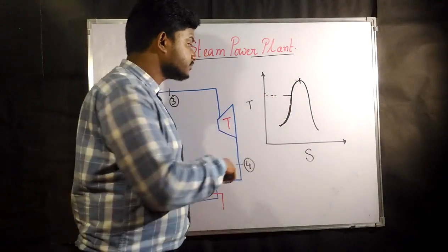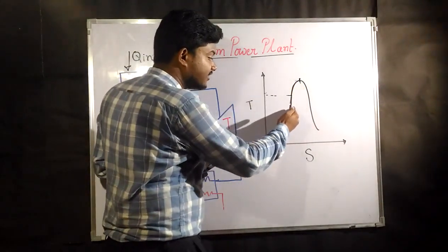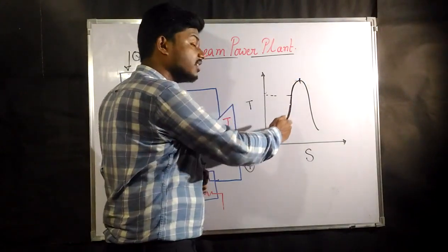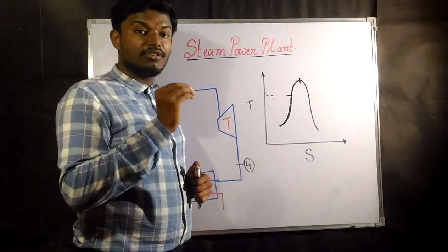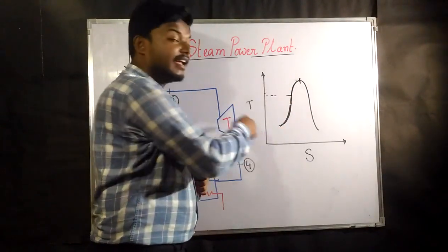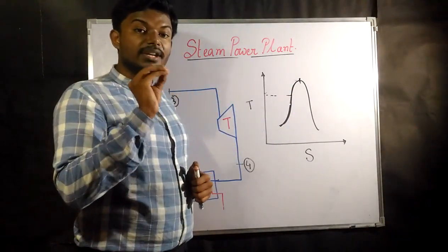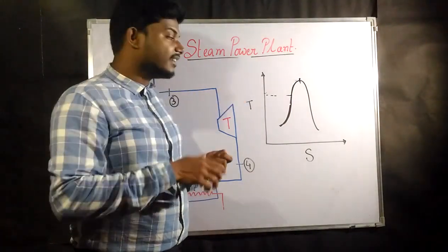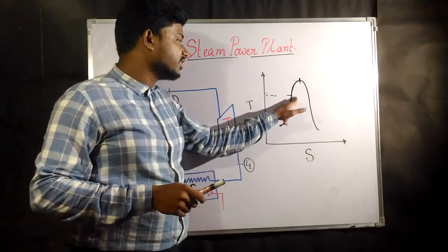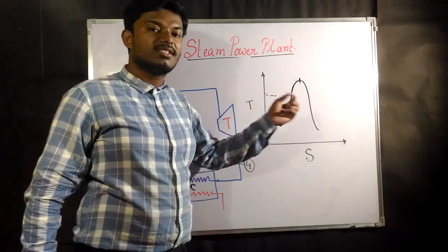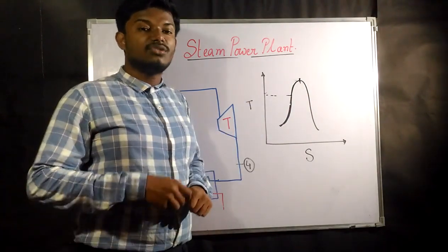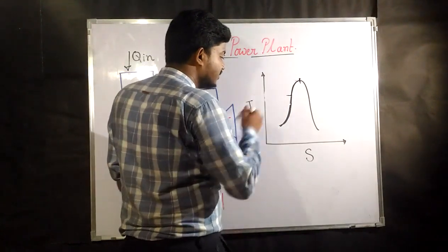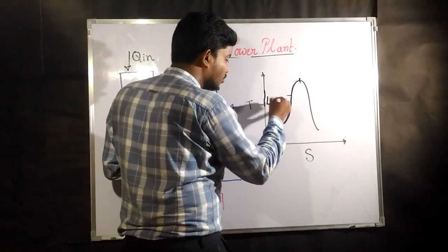Okay, this left line is a boundary, or a condition, for you to understand that at this point the liquid is going to have the phase of only liquid. If you slightly go inside this vapor dome, if you cross this boundary slightly, then your liquid is going to start to evaporate. So the left side is nothing but only liquid.